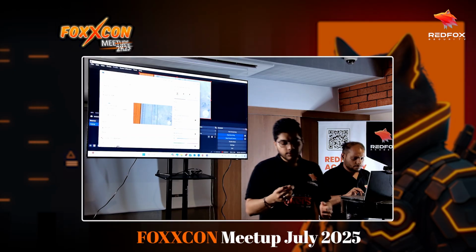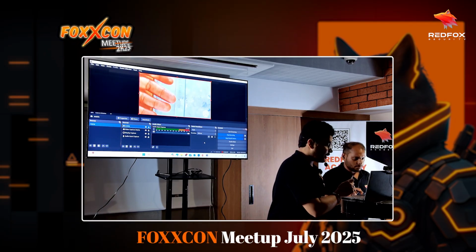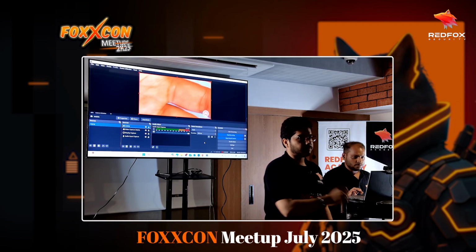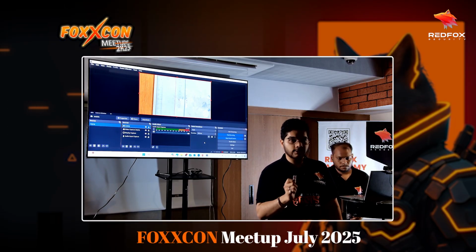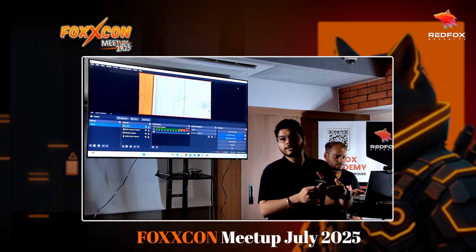Generally, you would think to connect these directly, let's say ground to ground, power to power, transmit to transmit, receive to receive. That would actually be wrong, because if two devices are transmitting together, they will not be able to read each other.